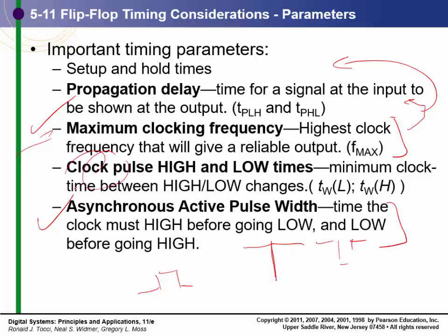And let me throw something out here that's a little bit interesting. If you're dealing with Altera devices, these are very stable. If you're dealing with an FPGA, which we have not talked much about in this class, such as Xilinx, that will route the circuits differently every time it routes a circuit, those could change from one compile to the next compile.